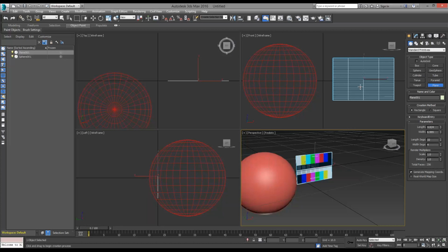If you export it, for example, with the export tool, then of course you will get each frame as it should be, but playing it back live on the timeline, you will see that it's just stuttering a little more. So it's a nice workflow to get used to having the polygon count in mind always. For planar surfaces, don't do this, and try to make it as polygon friendly as possible.